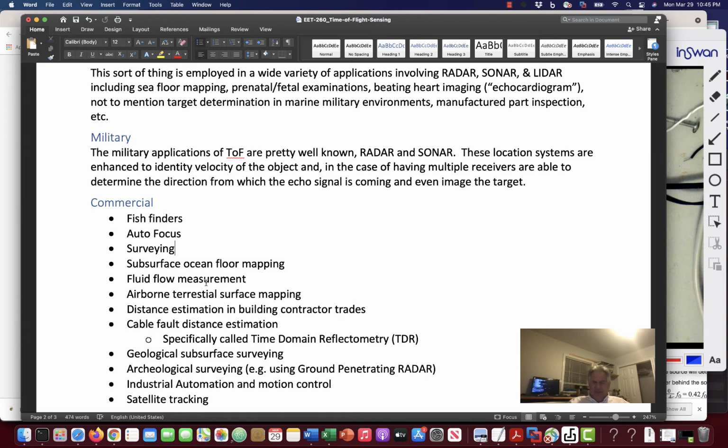Energy is sent out and then detected in its reflection, and you either get a time of flight, in which case you know the distance to something, or with multiple receivers, you get sophisticated processing and a terrestrial surface model for mapping.